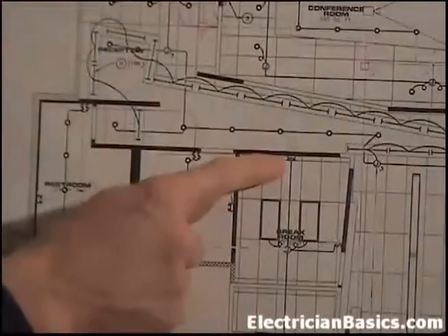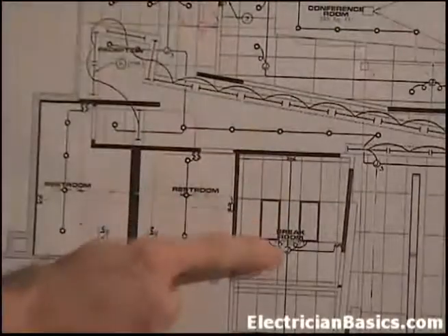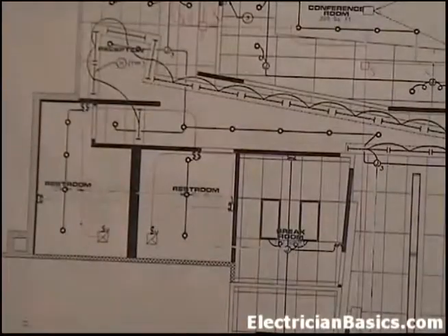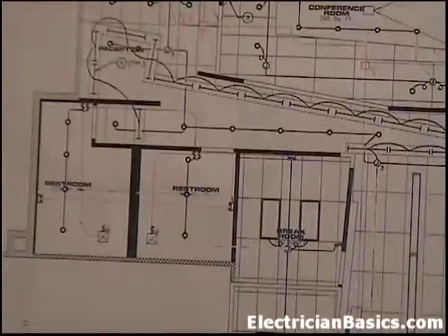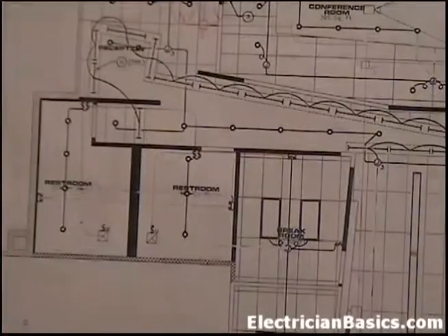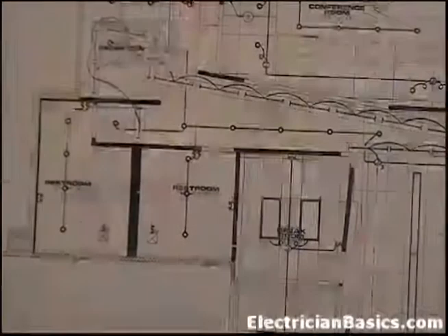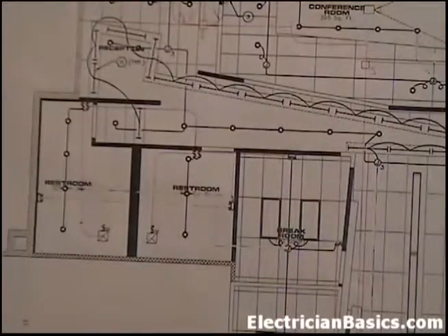Okay, look at this emergency light right here. If you follow this conduit all the way down through these lights in the junction box, once you go down a little bit, you'll see it's panel E4 circuit 1. And you'll have a home run for that. Okay, so that means that's the only circuit we're dealing with, and we didn't put any other circuits in that conduit. So we really don't have to indicate that as circuit 1 because everything on here is circuit 1.